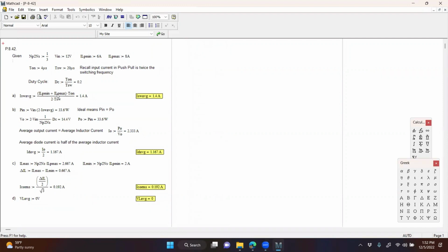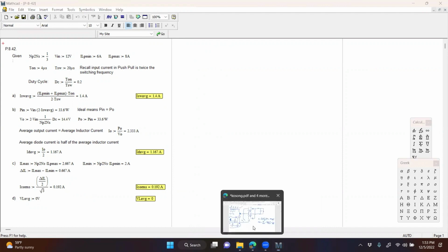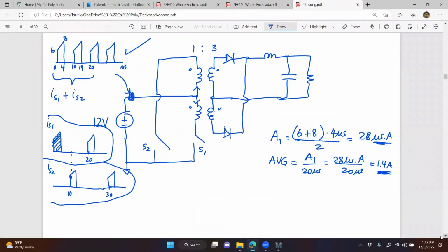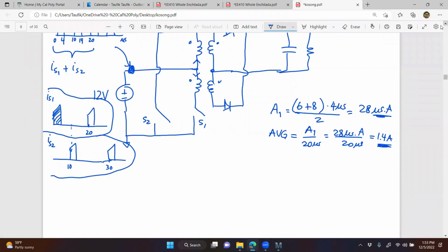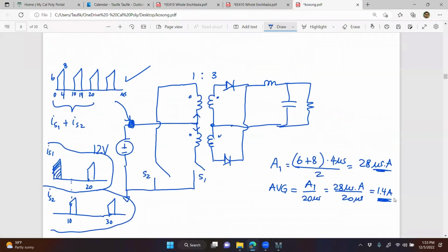You see this, right? Yes, I see it. So I use ILP min, ILP max, and that's what it is, right? It's the primary side of the inductor current. If you look at this trapezoid right here, the peak right there is the same as IL peak, the peak of the inductor current. But you reflect it to the primary side, so that's called ILP max.